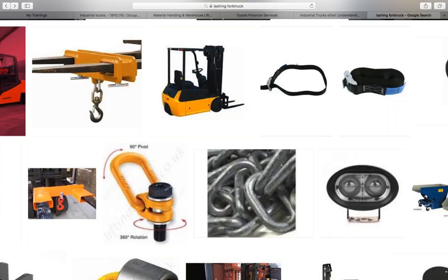We're going to go ahead and pull somebody in and have a signal person to help us, and to help us position the load. So it's not always just traveling, folks, but sometimes it's going to also be traveling with the load and or loading and unloading the load as well. And then, of course, in addition to that, use taglines, and make sure that we use taglines where necessary as well.